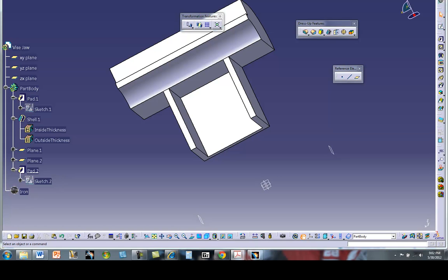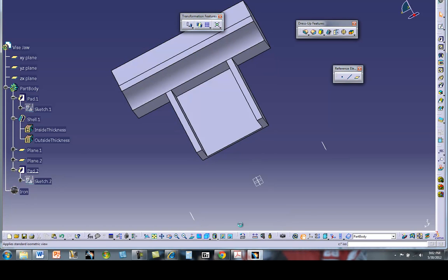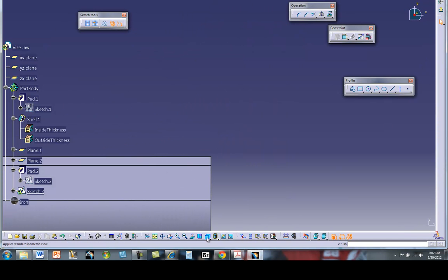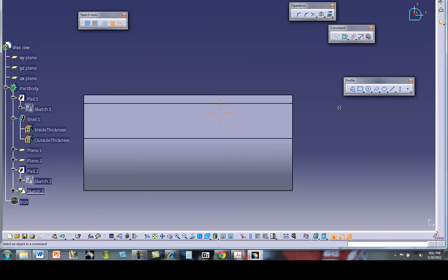So my sketch plane wants to be the very top plane of the object. So again, I'm going to my horizontal position. I'm going to grab this plane. I'm going to create a sketch out of that plane. I'm going to put it back, and so now that looks just as if we are in figure 4.95, just with a two-dimensional jump. So I'm sketching on this plane here. I'm going to change my viewing into shading with hidden edges so I can see through the object.